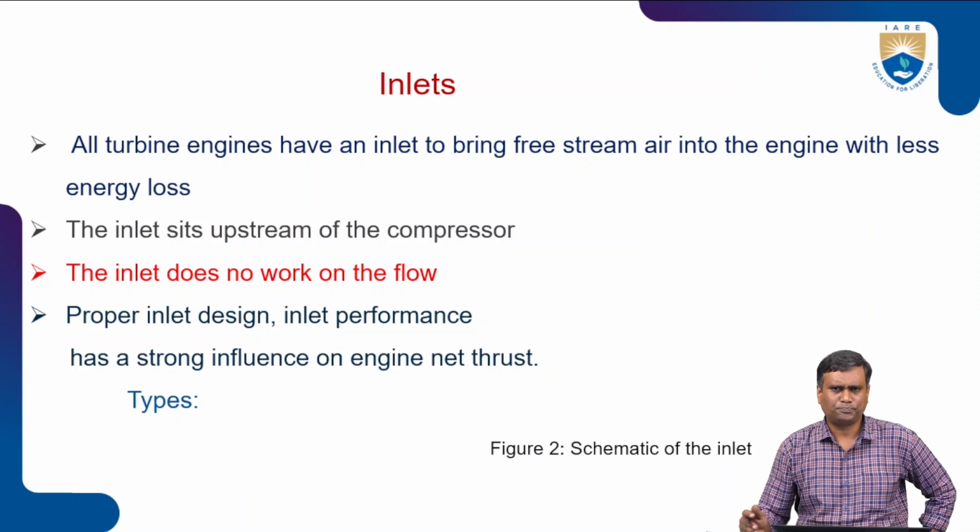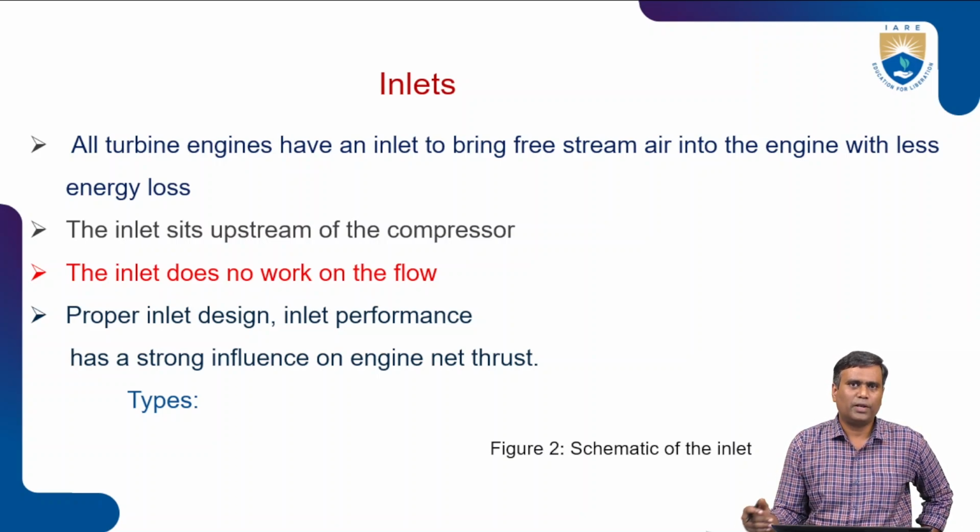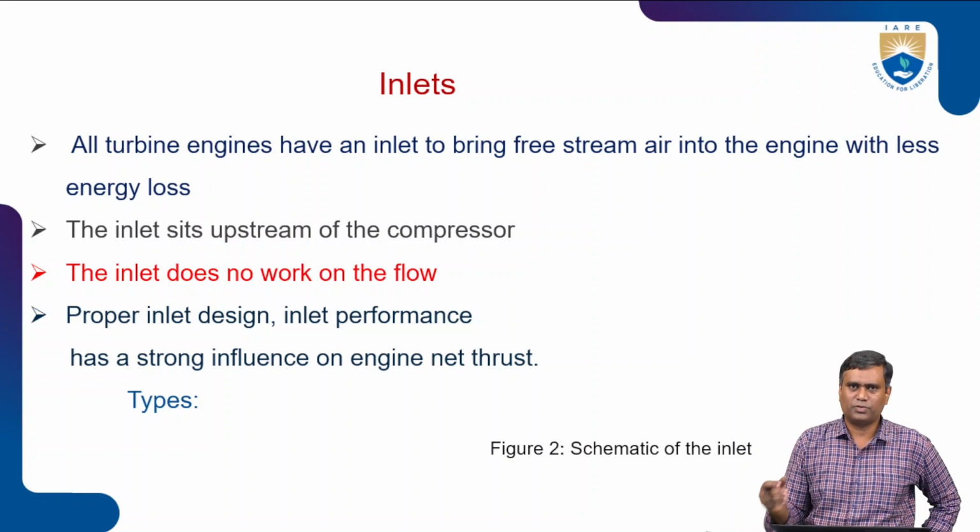A properly designed inlet should transfer free stream air with fewer losses, that is, fewer pressure losses and fewer velocity losses. Right. And at the same time, in certain cases, most of the times inlets will also compress the air and prepare the air before entering the compressor.